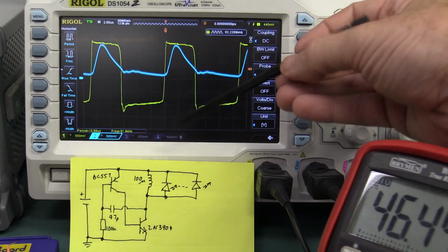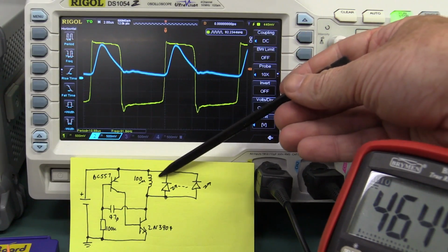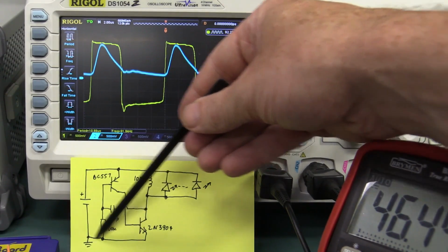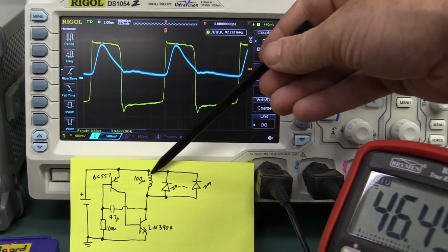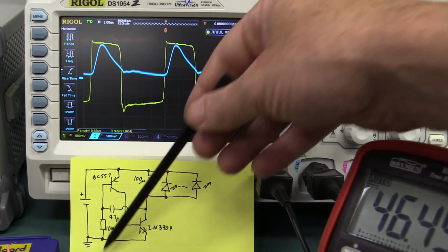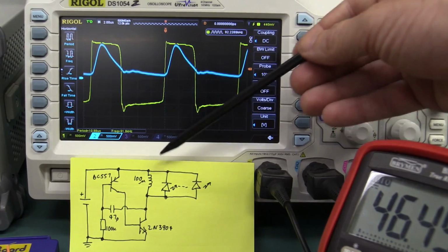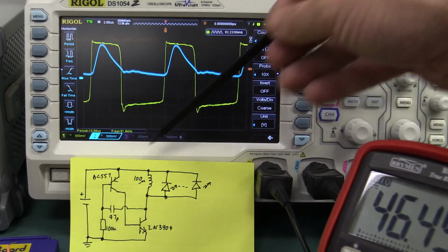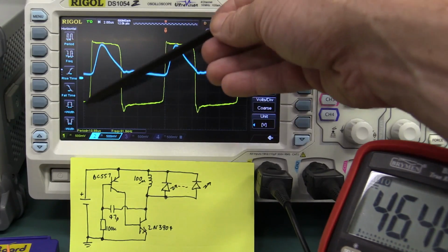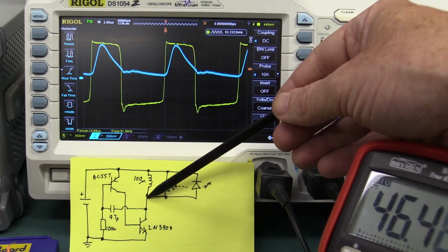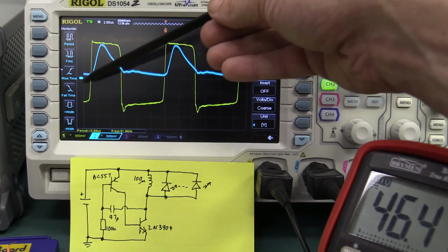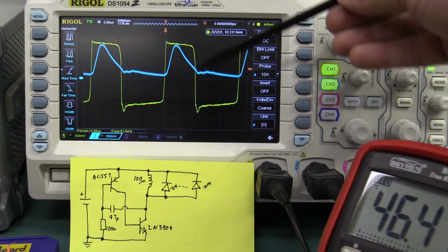And if we hook our scope up to the output of the microcurrent here, we have to be very careful. We can't just keep our ground probes down here if our microcurrent is in here, because then we'll short out our ground references across there. So I've had to now take the scope ground from there. You can do it with differential inputs and other things, but anyway, I just moved the scope input up here, so the yellow waveform is still measuring the voltage here, but it's referenced a bit different. And then the blue waveform now is our LED current.